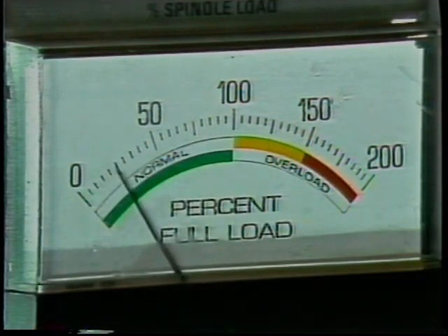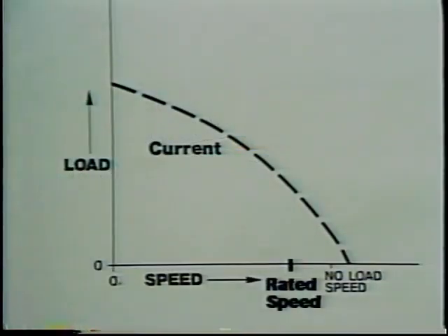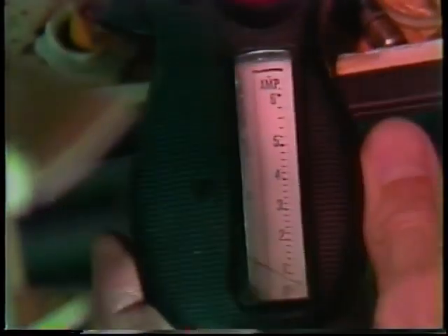That means that most motors can start and run under overload conditions. However, they will not reach rated speed, and that can be damaging, because below rated speed, a motor is drawing too much current. If it is stalled or runs too slowly for too long, it will overheat, and the insulation will be damaged. The overload breakers are supposed to protect the motor by tripping, but do not rely on them completely. If you suspect that a motor is overloaded, check its speed or the current to it.